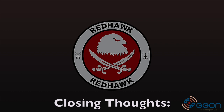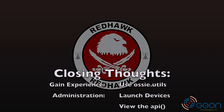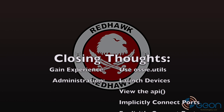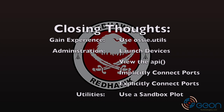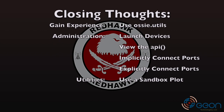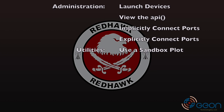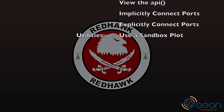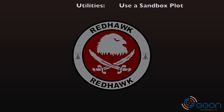So a quick recap. We covered how to access the Python shell and the REDHAWK Utils package to prototype a node, in a sense, by launching its devices. We used the API to verify one of the devices is what we were expecting. Then we used implicit and explicit connections by joining our devices together, as well as the TCP device to our new plot that we created from the sandbox. We then drove the whole design using the socket sign function to verify our connections were working.